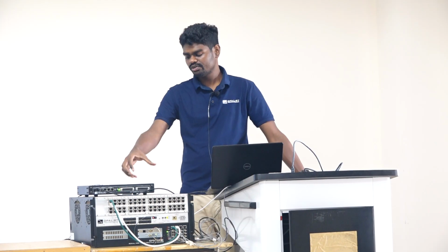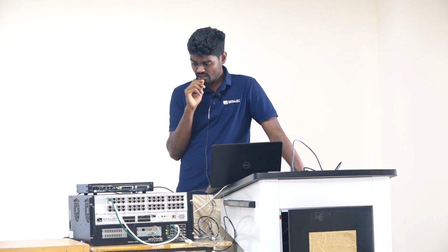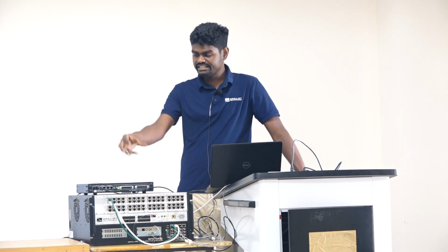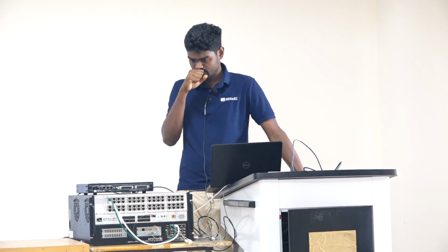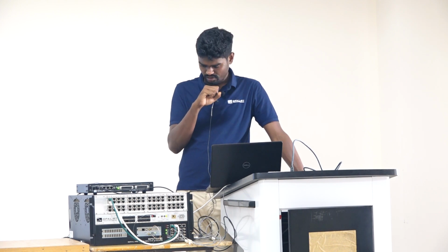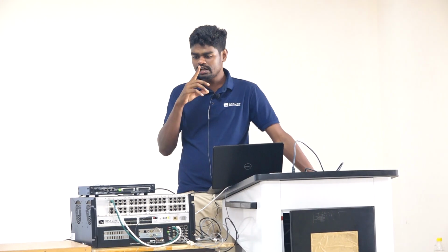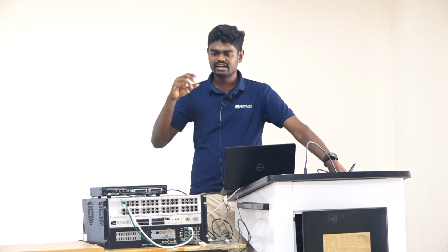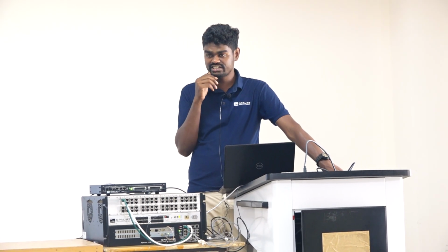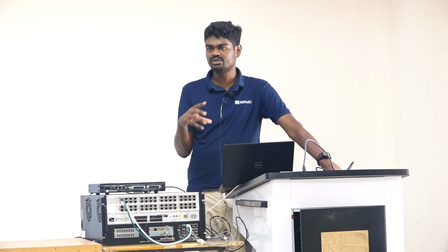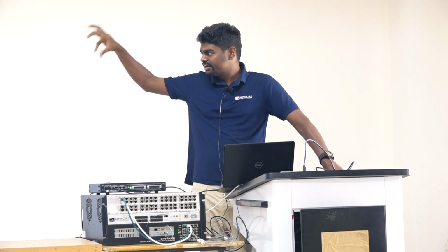Now I will go into the controller model. Controller OP8666: inside the controller you have the TI F28379D card. To run the models in this controller, you first need to install the MATLAB C2000 add-on. There is a library add-on in MATLAB specially for the Texas Instruments C2000 control boards. You need to install that, and you need to take some custom block sets.